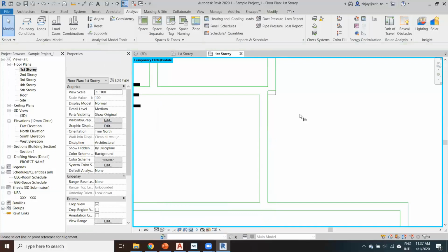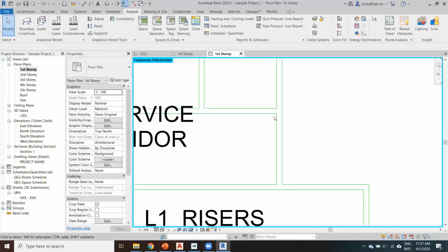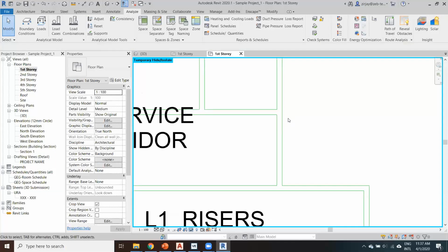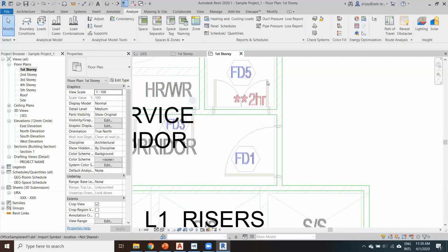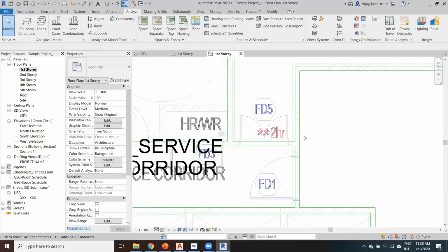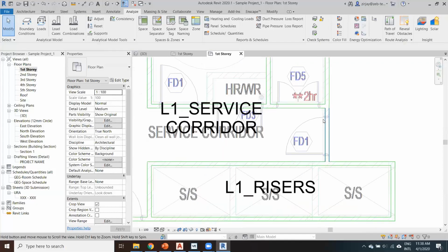So there's no harm trying to align this wall, even though in the CAD plan, the architect's intent is to have that kink. In our case, it's not going to affect our energy model that much. So it's okay to deviate away from the architectural drawing in that regard. It's just a small kink. We can just assume it's aligned.